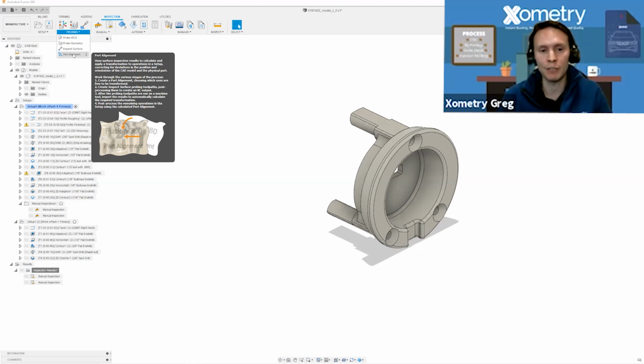Provide a report that feeds back to their dimensions and measurements, so those GD&T dimensions and those other features. So if you do have an inspection system that can do that and it's calibrated and you can provide proof of calibration, that's a go, right? But if you're using it for verification, but it can't do things like true position or a surface profile and measure to that level of detail, then you'll need a secondary inspection method.